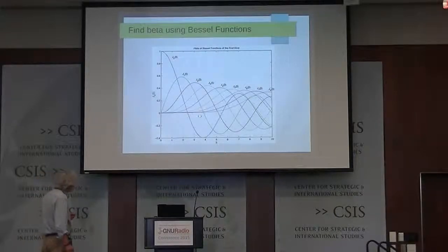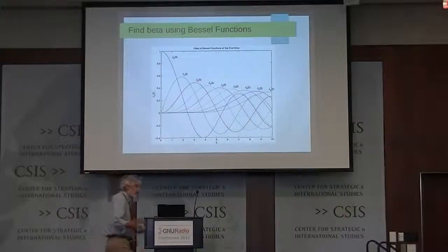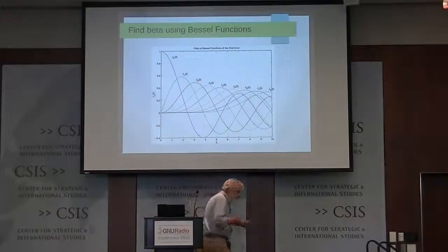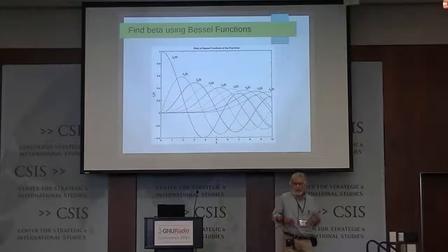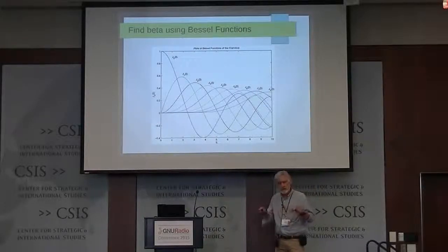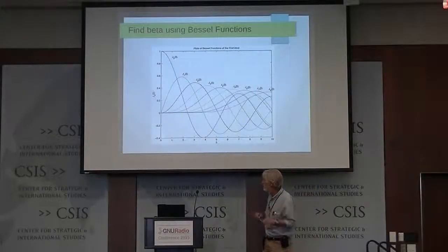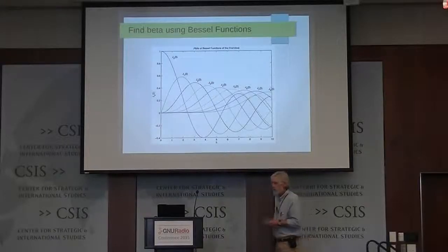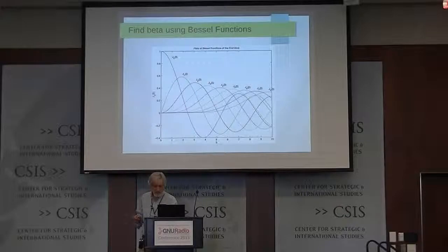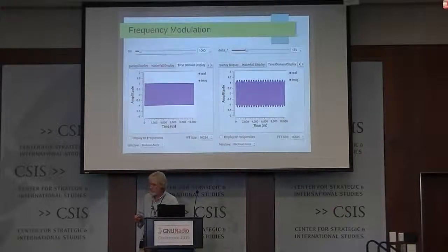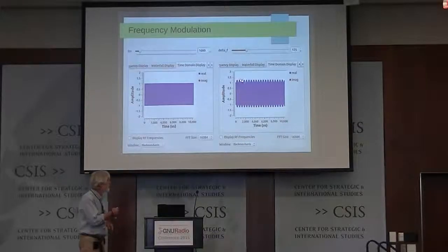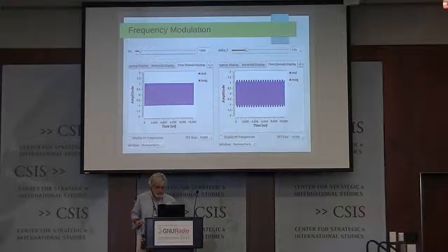So we are roughly at about 3.8 or so as the modulation index, and from there, you can compute the maximum frequency deviation, and you can verify that with the components that you actually put into your block diagram. Okay, here's a picture of the two waveforms. You can see that it's not an entirely ideal signal that you're creating this way.